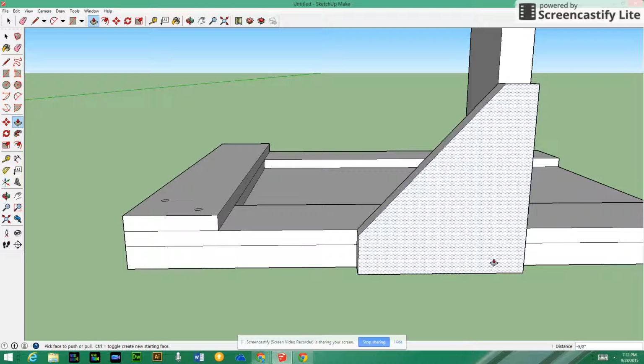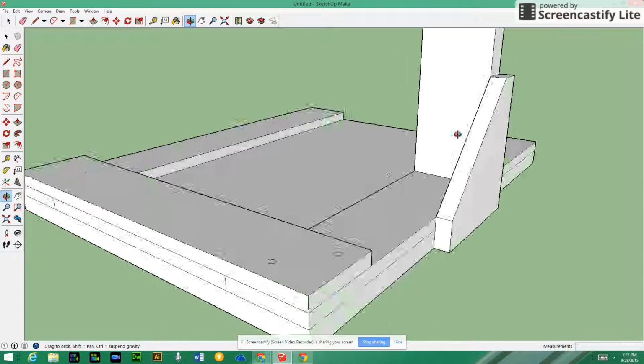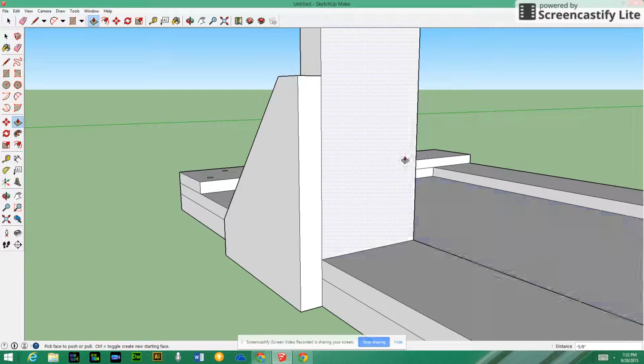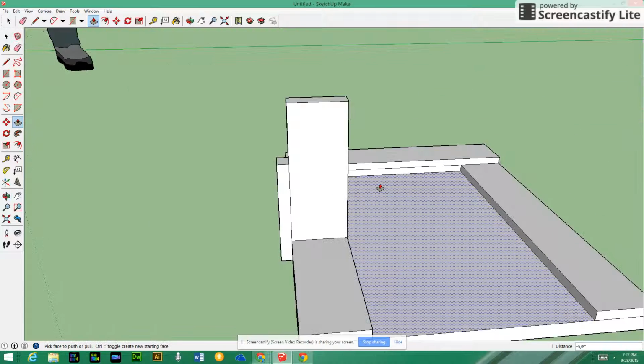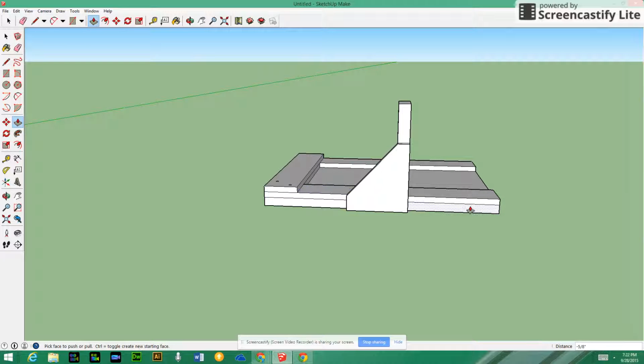If you want to put a couple nails in both spots, again, it creates a triangle, and the triangle will create a rigid shape for your object. You might want more clearance in here, or maybe it's just the design idea that the way it looks better. Maybe you think the lines look cleaner. So that's just another way that you can set up and design and make your columns. You can have supports coming out both ways if you want. I've seen that where there's a triangle coming out the other side as well.